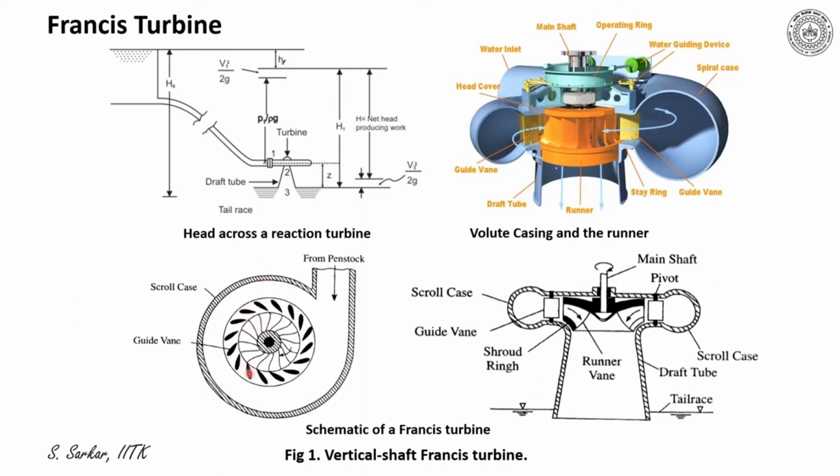Furthermore, one can appreciate the impeller here. In another section, one can find the guide vane and the impeller, and here you can see that the direction of the flow within the impeller passage changes from radial to axial. That's why the impeller is a mixed flow impeller here, and then the water is pushed to the lower reservoir via the draft tube.